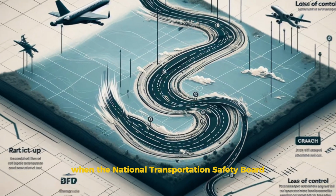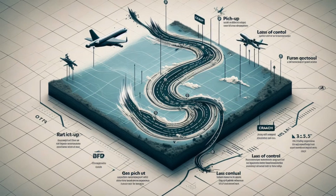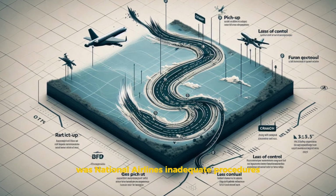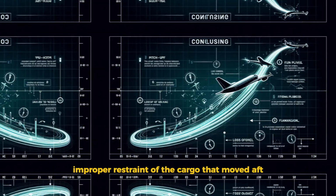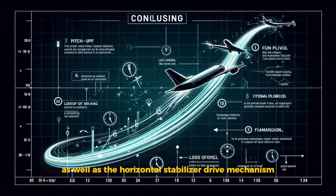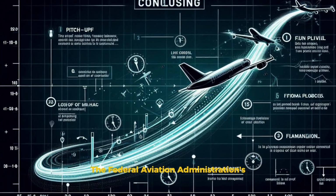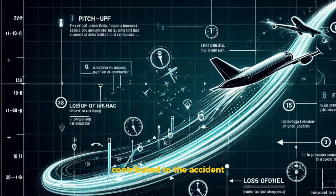When the National Transportation Safety Board issued its final report, it reached the following conclusion. The National Transportation Safety Board determined that the probable cause of this accident was National Airlines' inadequate procedures for restraining special cargo loads, which resulted in the loadmaster's improper restraint of the cargo that moved aft and damaged hydraulic systems 1 and 2, as well as the horizontal stabilizer drive mechanism components, rendering the airplane uncontrollable. The Federal Aviation Administration's failure to monitor National Airlines' handling of special cargo loads contributed to the accident.